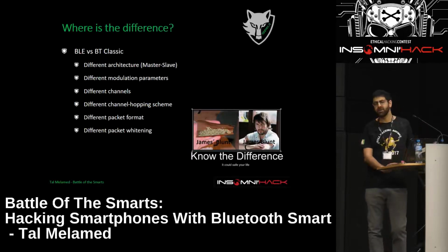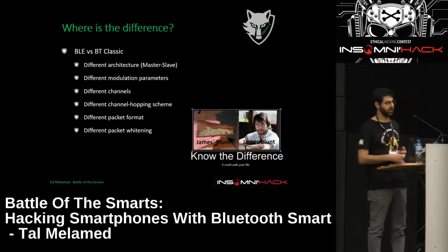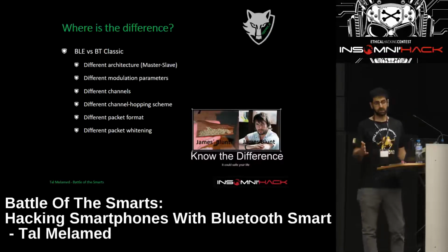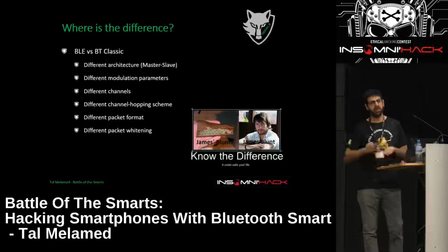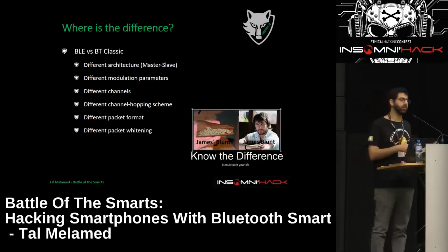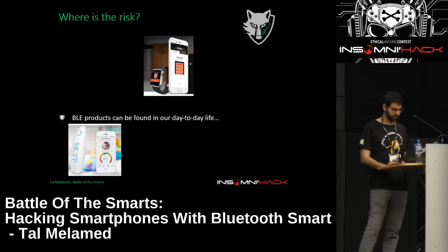Okay, what is the difference between Bluetooth Classic, the original Bluetooth that we know, and BLE? So they're totally different. They cannot talk with each other. It's a different protocol. They have different architecture, different modulation, different channels, different packet formats, etc. So when we talk about BLE, it's actually Bluetooth, but it's a different protocol. So it's not backward compatible.